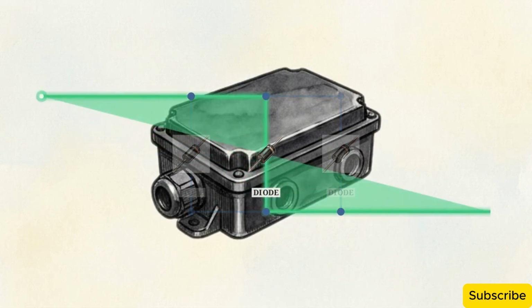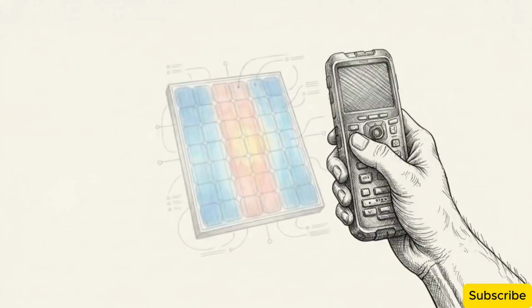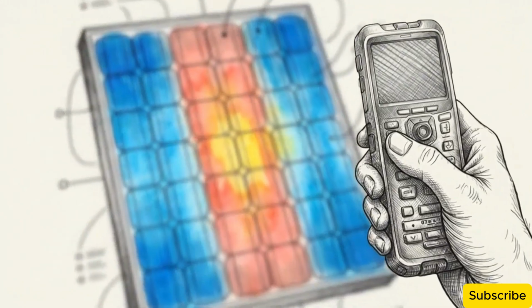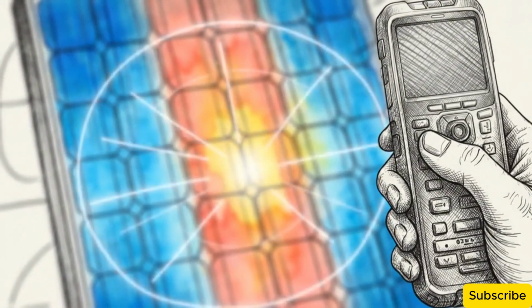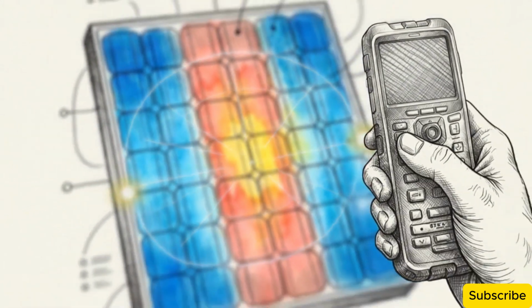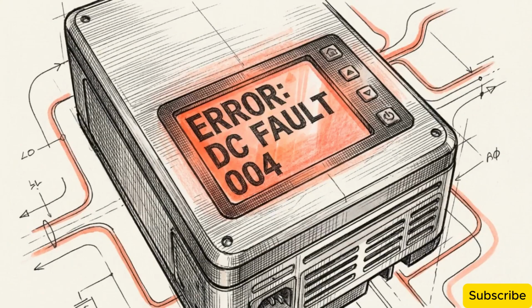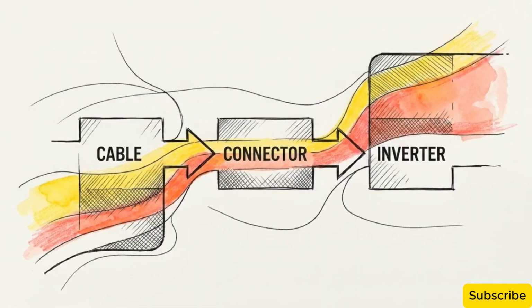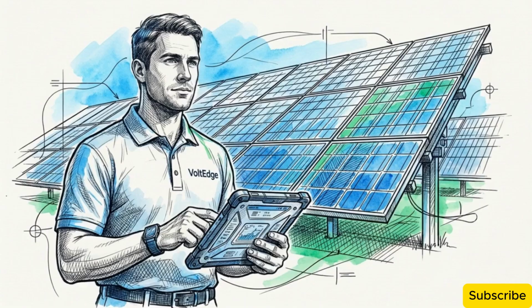Right on the back of the panel is the junction box. This houses the bypass diodes, which act as the safety valves for the panel's internal power routing. If a bypass diode fails, it acts as a hard roadblock for that specific section of the module. This disrupts the output so severely that it often triggers a system-wide error code at the inverter. Trace the circuit from source to load. What looks like a dead panel is often a healthy solar cell trapped behind a broken electrical chain.